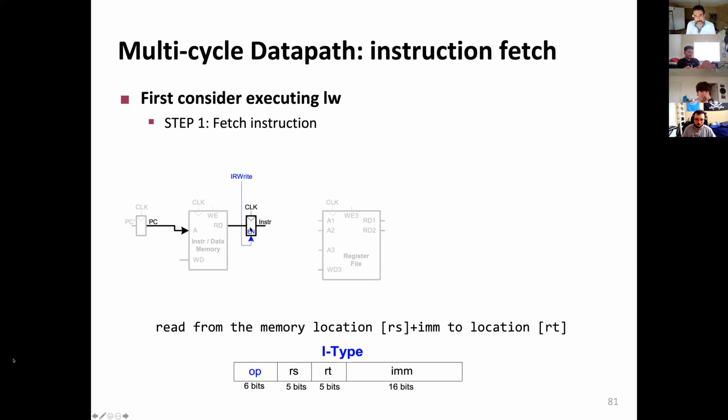And then here you see a new thing. You can think about it as a register. Registers are implemented by flip-flops, right? So these are digital logics that enable you to store data. So what data do you store? The instruction here. You store whatever you get from the memory into this register, and that's step one, in one cycle, for example. So by the end of this cycle, you have some data in the register, okay? That's good.